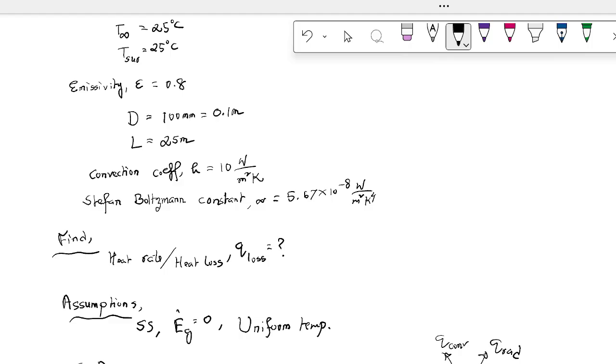The convection one is the convection coefficient h multiplied by the change of temperature, which is Ts minus T infinity. You know what Ts and T infinity are, right? In the givens you wrote the Ts and T infinity, so you know that. Again, the equation is h multiplied by Ts minus T infinity, multiplied by A, the surface area of the pipe where we're losing heat. That's the convection. What is the radiation? You remember the radiation equation from the pipe to the surrounding? Epsilon, sigma, area.